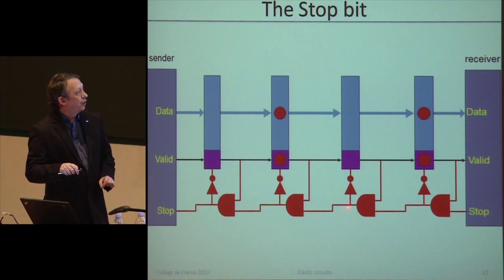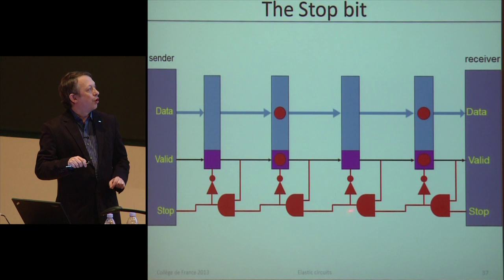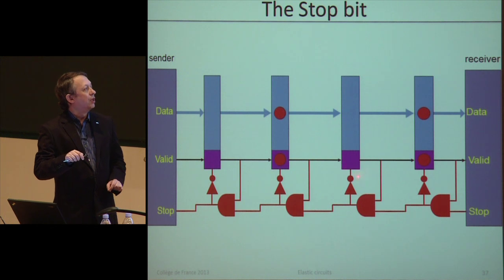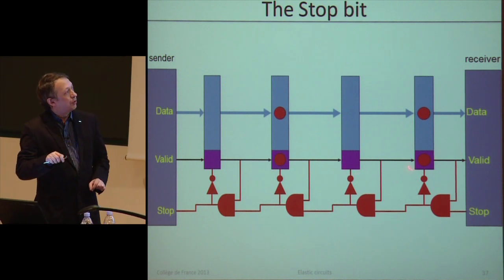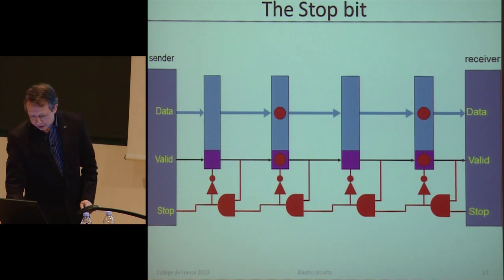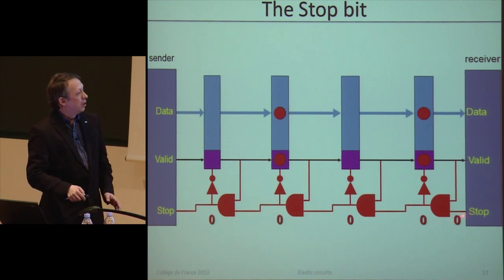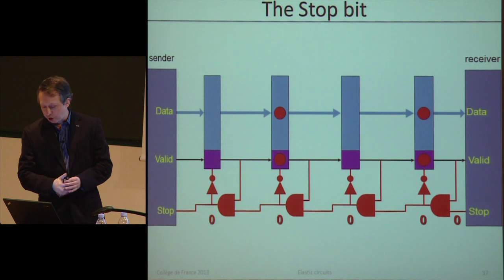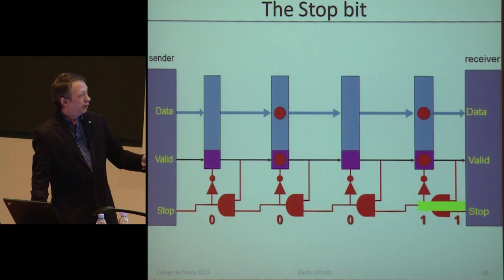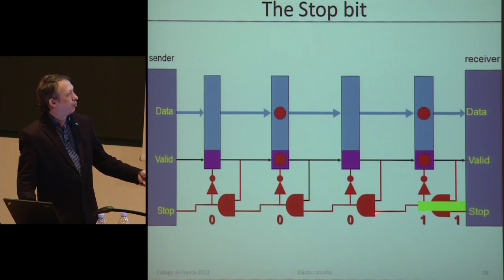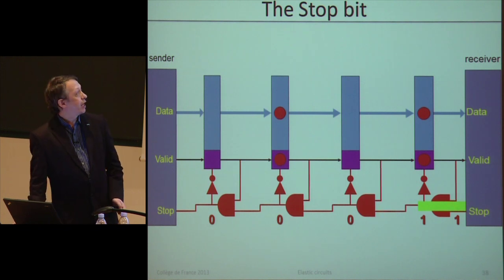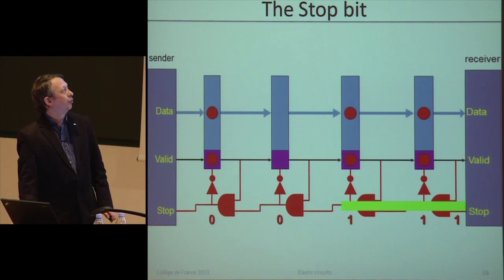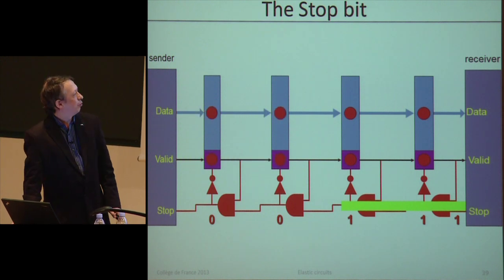It indicates, so if we think about the complement of this signal, so the signal will be valid if it is valid and it's not a stop, so this will be enabled. It will be disabled when the previous is a stop and has valid data. And for example, if the stop is 0, then no problem, the pipeline will work, all of them will be enabled. These zeros here will be ones here, so all of them will be enabled. But if it says a stop here, then this stop will propagate until we find the bubble. So in the next cycle, we will move data one step forward. Okay, this stop will propagate backwards, and we will move data one step forward,